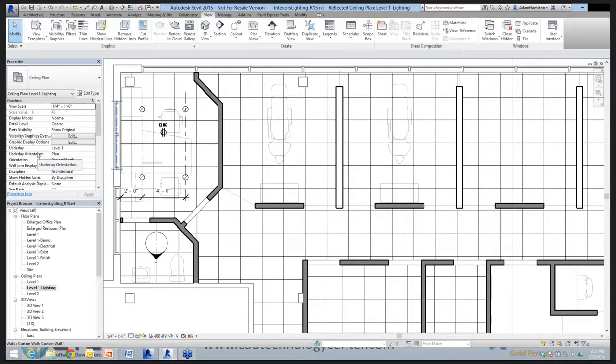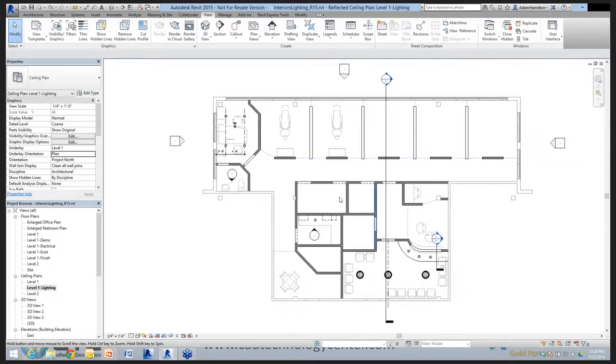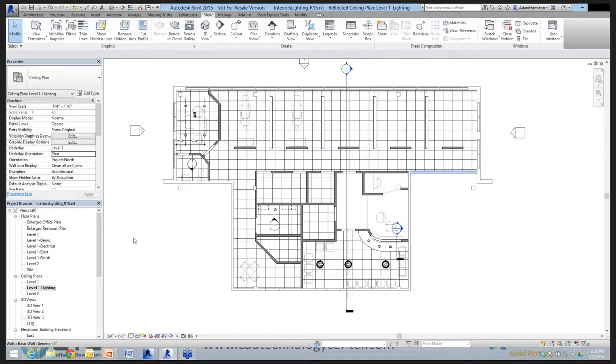However, you can change the direction of the underlay between plan or ceiling. From a reflected ceiling plan, we'd lose some of those settings, or we'd be looking in the opposite direction. So sometimes we need to switch it around to plan view. And when that's in and applied, it will have an effect on the background that gets brought in. So we can utilize this to do our layouts.